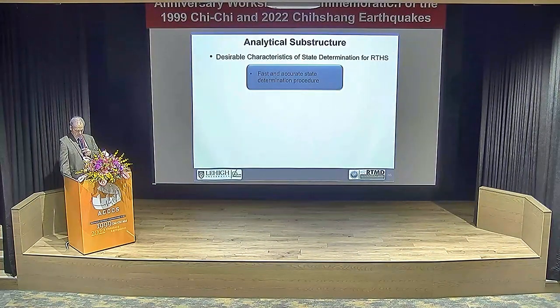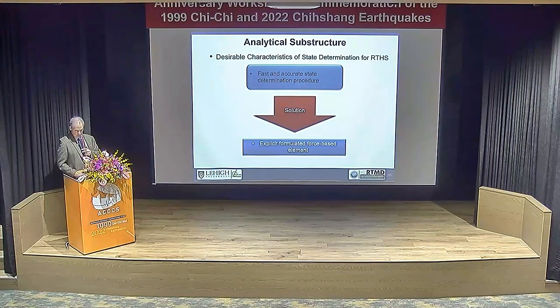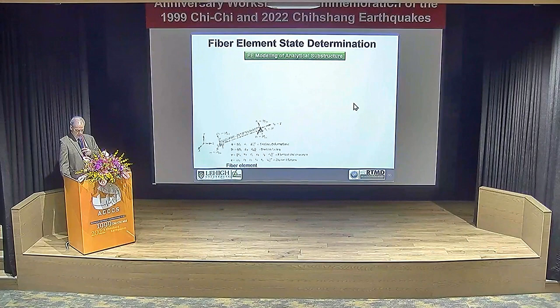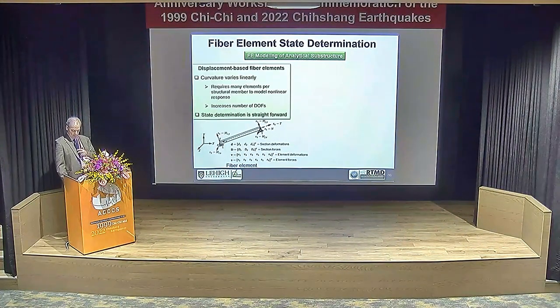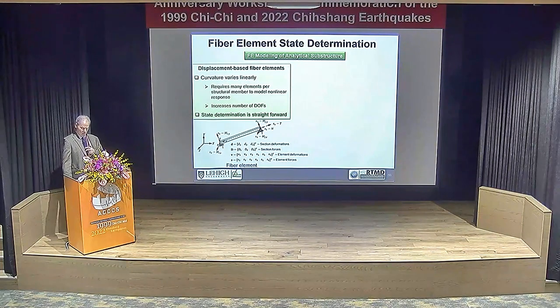So the analytical substructure, I'm thinking not necessarily shear walls, Jack, but those are important. Thinking about frame members where fiber-based elements work reasonably well. One of our solutions there is to use what's called force-based elements, and so conventionally, there's two types, and maybe even more, of elements. One of them is displacement-based.